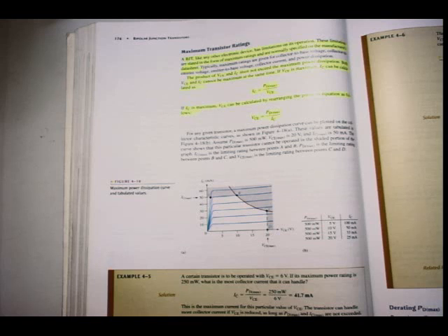The product of VCE and IC must not exceed the maximum power dissipation. But of course, both VCE and IC cannot be maximum at the same time. If you recall the characteristic curve that I have of IC against VCE and the load line, as I move up and down on the load line, if I move closer to 0, then VCE will be less, but IC will increase. And if I move down on the load line, you can see that my IC will become less, but VCE will increase. So they cannot be both high at the same time. That's all that they're saying here.